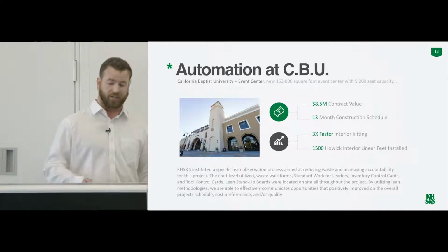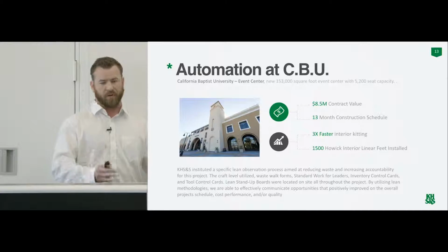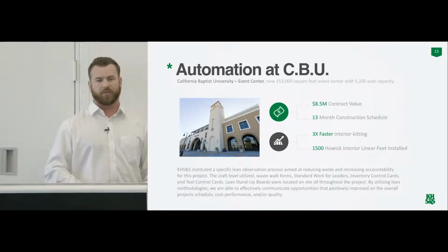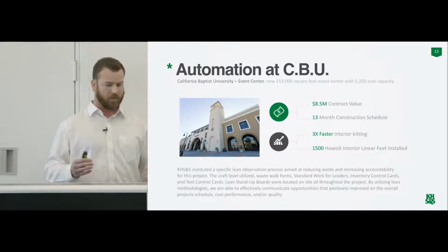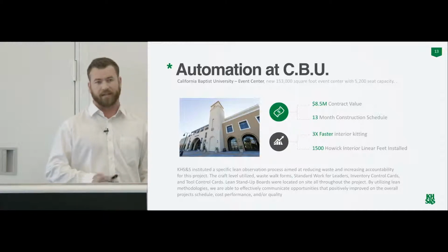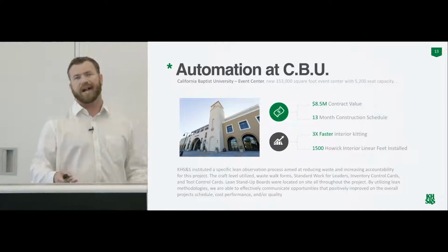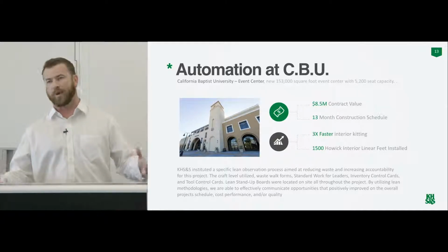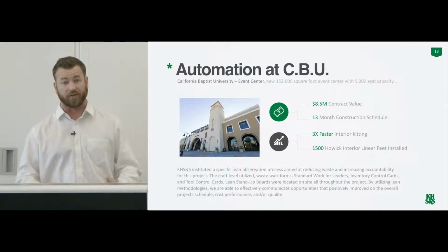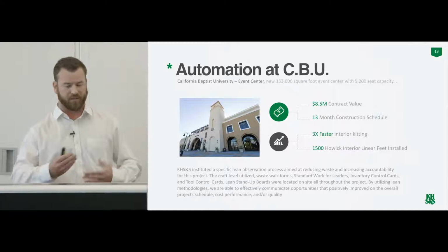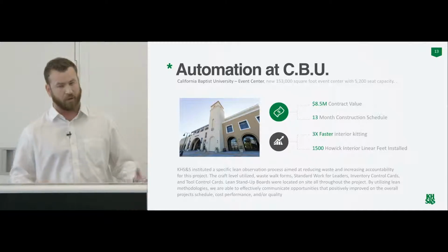So what we did for this situation was we developed panels, output CSV files, very precise layout drawing saying this panel goes where, the Howick labels the studs, and we sent this out as a kit of parts. So it wasn't panelized, we didn't build it in the warehouse, but we did send pallets of these basically kit of parts out to the job site.